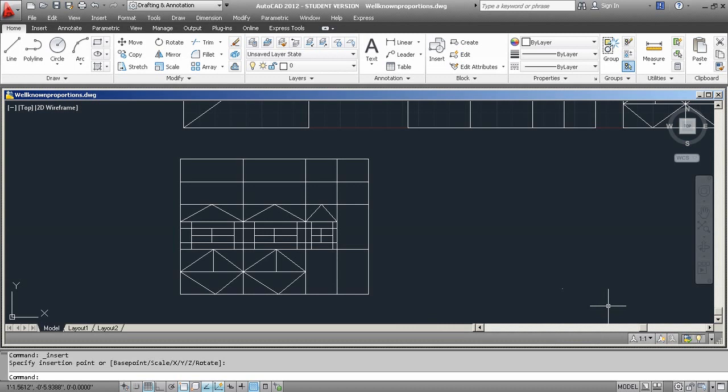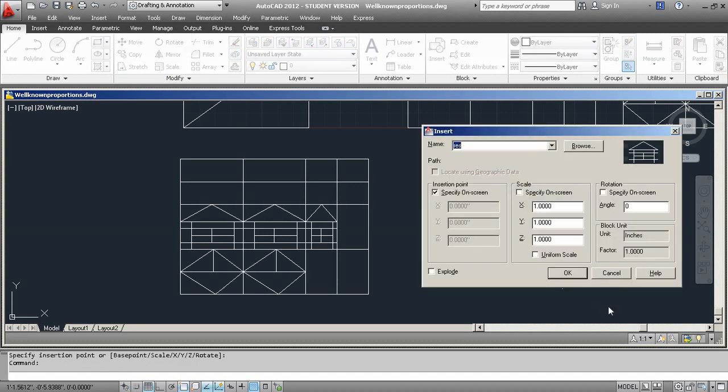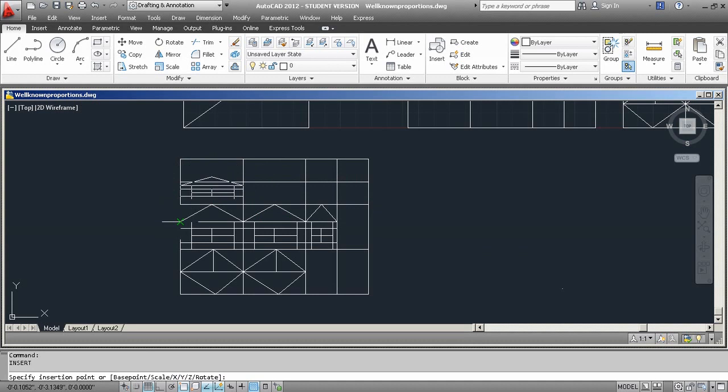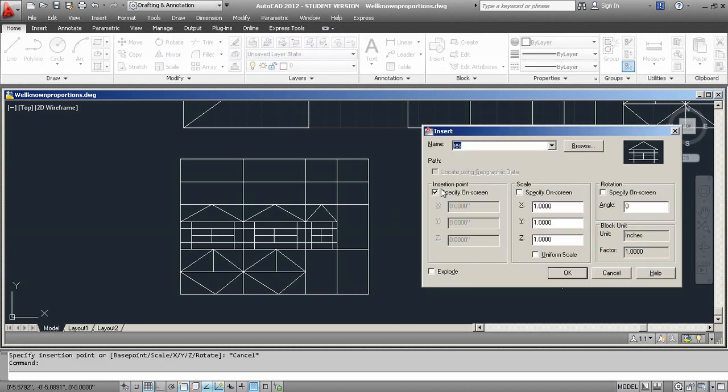We're going to use the same technique and make blocks and insert the objects proportionally in either the X or Y directions. Making blocks and inserting them at different proportions is one of the smarter ways of doing this project using AutoCAD. Of course, you can draw everything freehand, but it's much easier to make blocks and insert them in different proportions. It's more productive too.